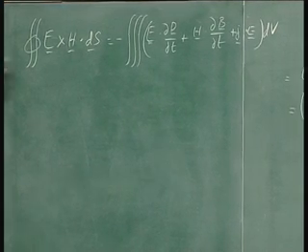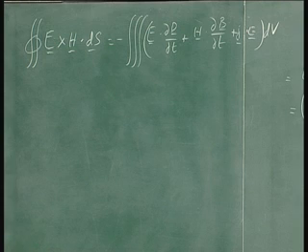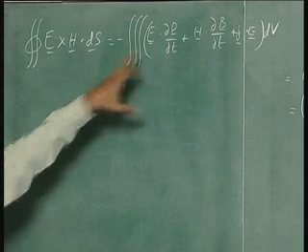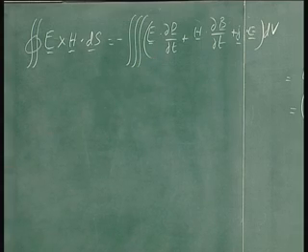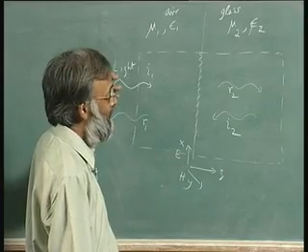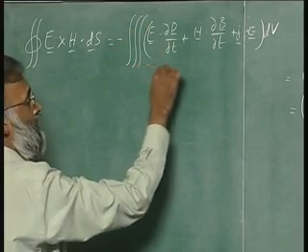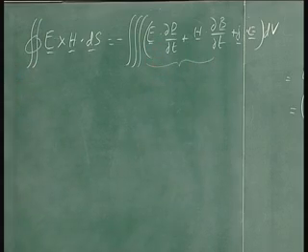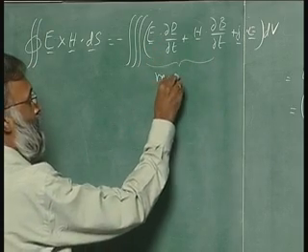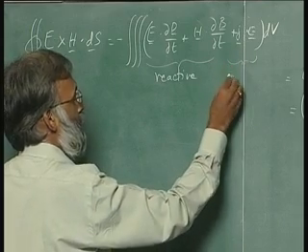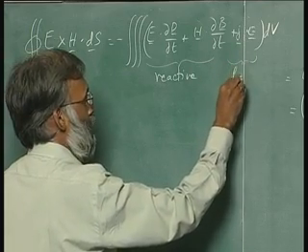And we looked at it last time in phasors, and what we found was that if you looked at the real part of this, these two did not contribute. That is, if we have waves that are sinusoidal waves, then we can write down a phasor equation. And what we found was that these two pieces gave only the imaginary part. So, they are reactive,